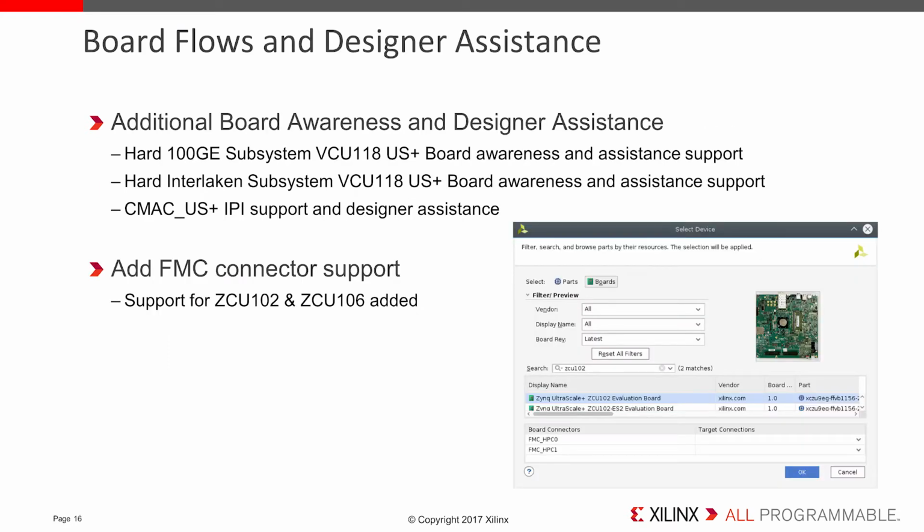Additional board awareness and designer assistance are now available for hard 100GE and interlaken subsystems for VCU118 UltraScale+ board. There's also added FMC connector support for ZCU102 and 106, intended to extend the target board selection process for FMC cards.